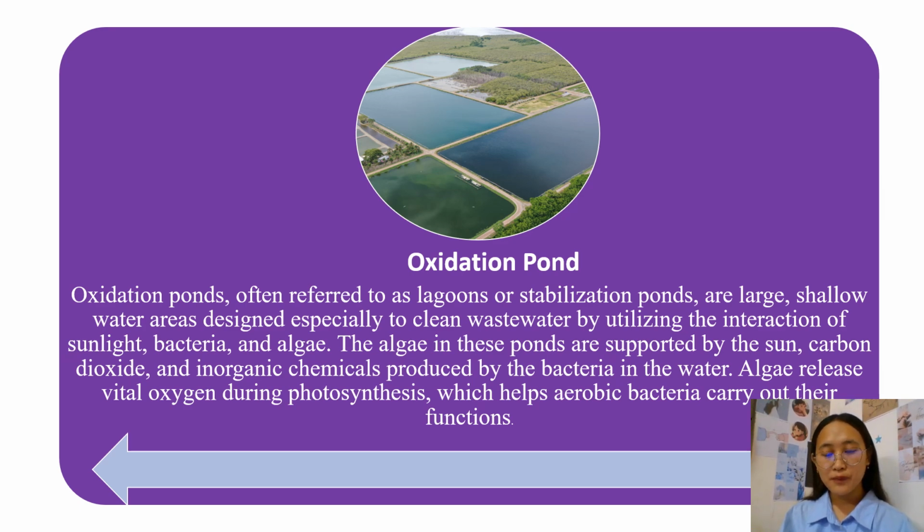The algae present in these ponds are supported by the sun, carbon dioxide, and inorganic chemicals produced by the bacteria in the water. So algae release vital oxygen during photosynthesis, which helps aerobic bacteria carry out their function of degrading the organic compounds.